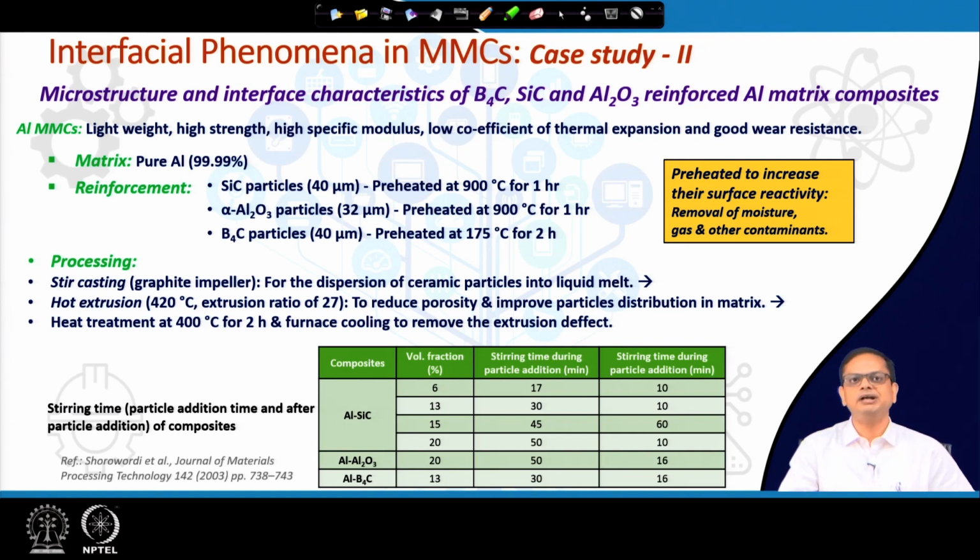It is a casting technique augmented with a stirrer, so that there will be homogeneous distribution of the reinforcement particles, which in most cases are of lower density and tend to float at the top or segregate during the stirring. Particles of different densities from the matrix should be homogeneously distributed in the matrix, and that is why stirring comes into the picture.